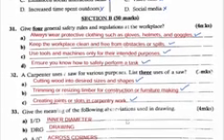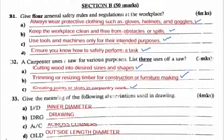We continue to question number 33. Give the meaning of the following abbreviations used in a drawing. You have I/D means inner diameter. So when you see I/D, it means inner diameter. We have DRG. DRG means drawing. We have A/C. This means across corners. And lastly, part D, we have OLD. O to stand for outside, L length, and D diameter. So OLD means outside length diameter.